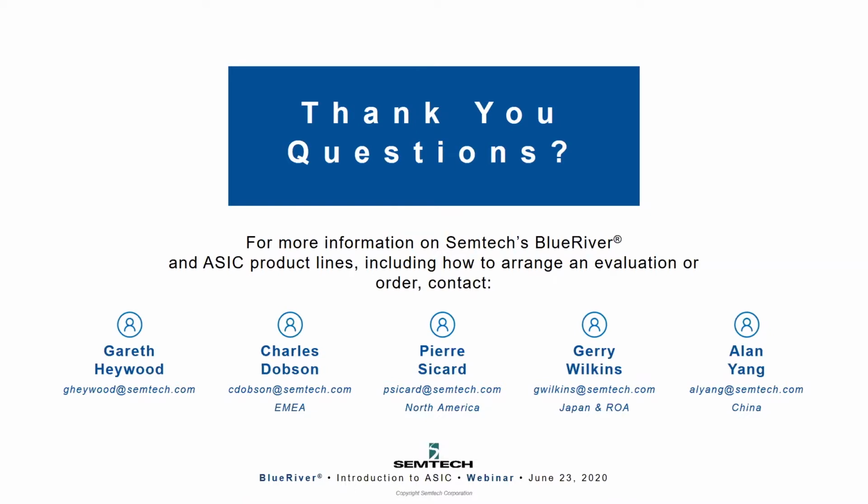Okay, so then a follow-up question from the same person. Does HDMI to IP support all InfoFrames, including dynamic metadata for dynamic HDR? Absolutely. For example, HDR10+ and Dolby Vision. Yeah, absolutely. So that's a key capability of BlueRiver. We do ensure that what comes in is what goes out. So in terms of any kind of HDR format, we do ensure that all the InfoFrame information is preserved.